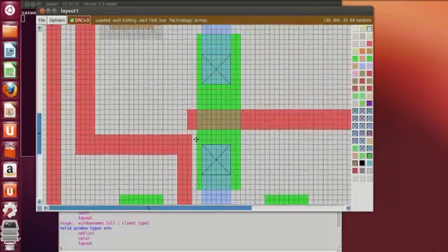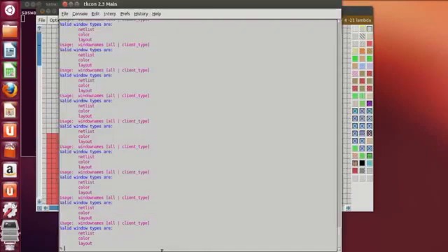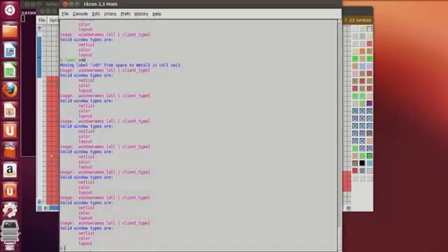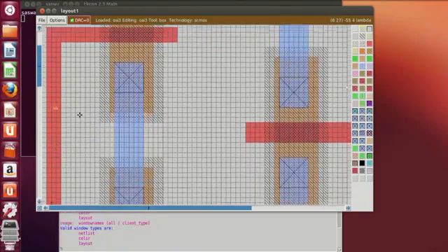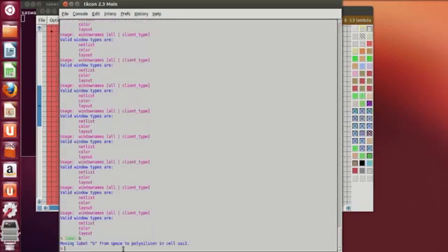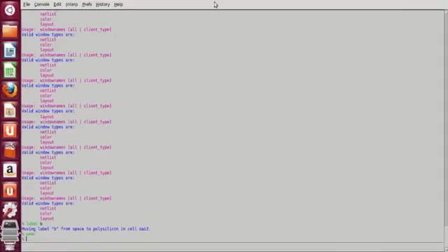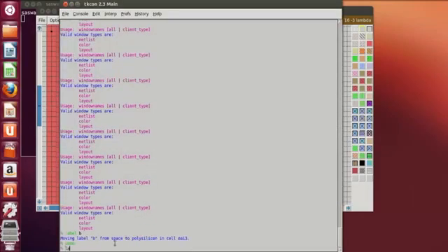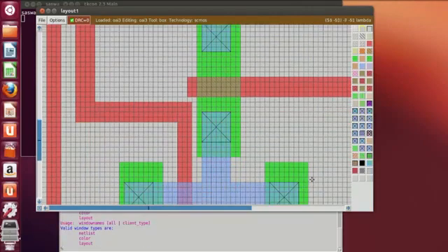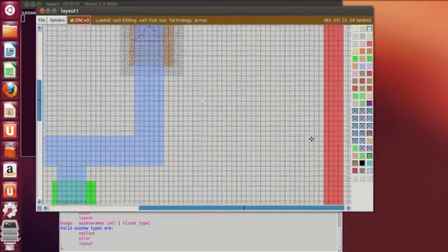Then after labeling ground, label the VCC, label VCC, that is VDD. Then after labeling the VDD, this is the input A, so type label VA, this is A and this is B. So okay, let's undo. Label VB, and then this is VC.